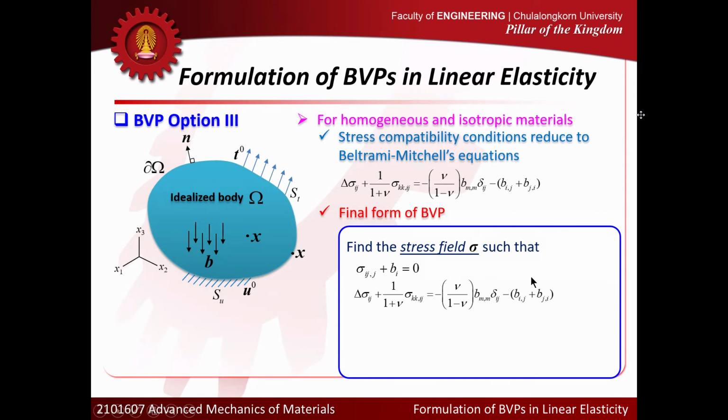the body. And also the stress field has to generate the displacement field, or the displacement field has to exist, right? So to confirm that, the stress field has to be compatible, or the stress has to satisfy the Beltrami-Mitchell equation, so that it ensures the existence of the displacement field. So these are the two governing equations for the stress field.